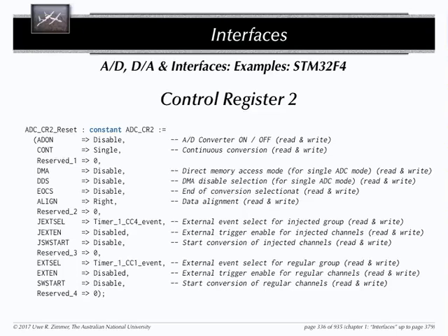How big is your crystal? You can show it with your fingers, so it must be millimeters, right? Stuff in the dimension of millimeters usually doesn't go on chips. So your crystal is the one bulky elephant in the room which you cannot possibly put on the chip itself, because it's many orders of magnitude larger than anything else on that thing. So the crystal is the only thing which is outside of it. It is not part of the microcontroller. It has to be outside.